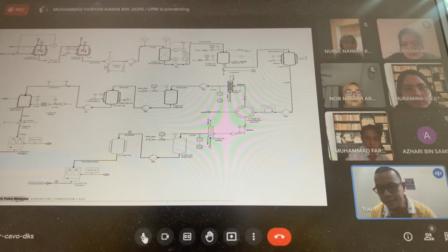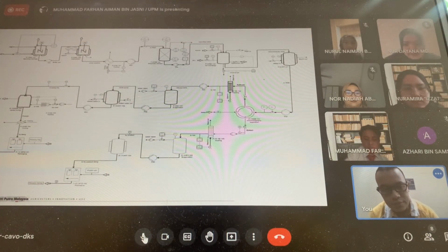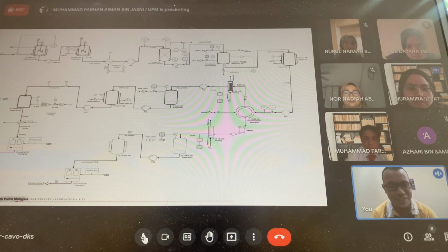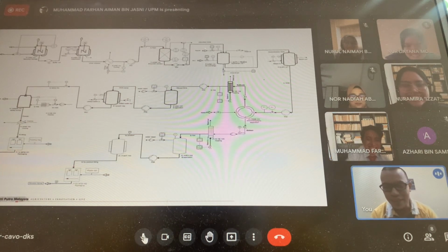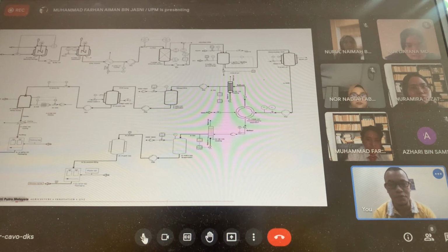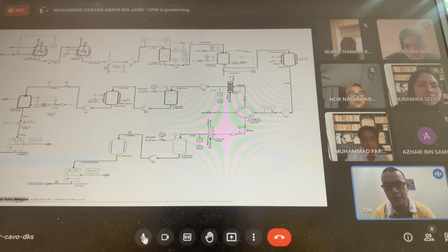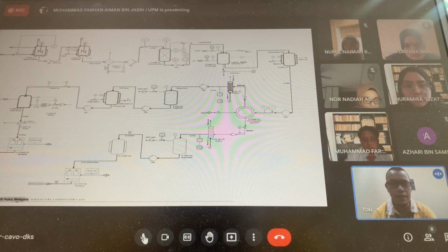So this is the PID. This is the PID, right? Yes. So this is the PID. As we mentioned before, usually your PID is a very simple, straightforward process. And as mentioned before, the reactor must be jacketed. Another one is for the filling at the packaging area, that is mentioned here, you have to have a load cell.